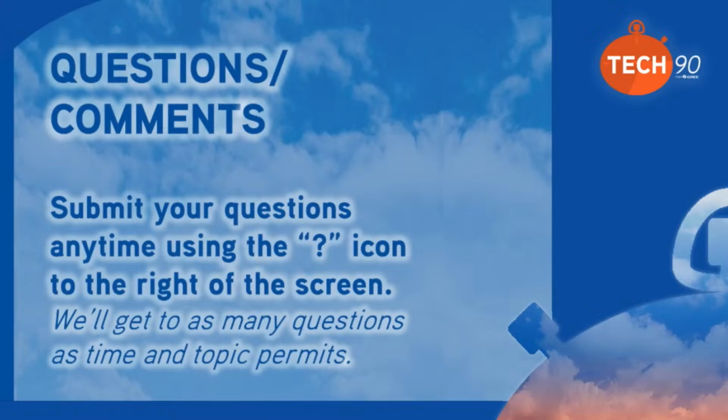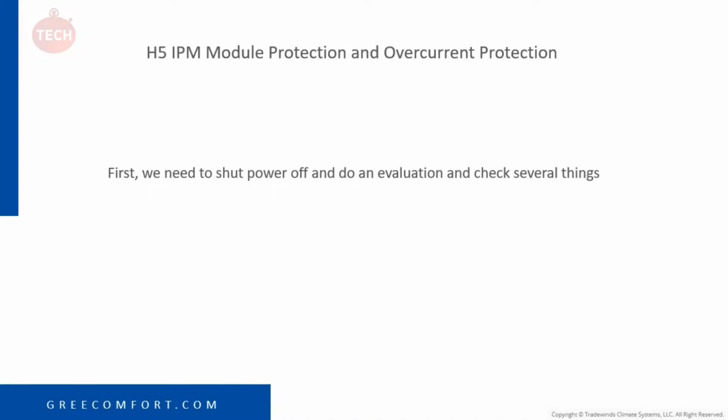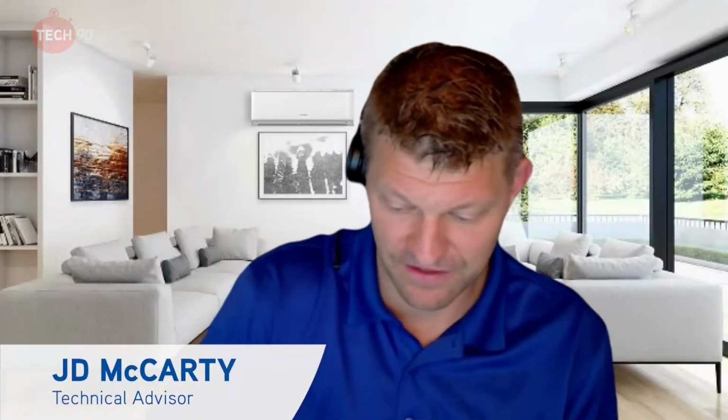All right. So now we're going to get into our last code. It's an H5 code, which is IPM module protection and overcurrent protection. First, we need to shut off power and do an evaluation and check out a few things. So this, again, is a hard reset code. So 10 minutes of off time.